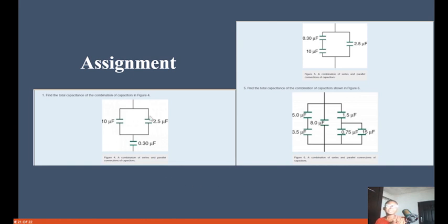So you can see this now. These two, you check, are they connected in series? Yes, these ones are connected in parallel. Then you are going to resolve it, and this one which is connected in series too, you have to resolve this first and change it to series before you can come and solve this. You know, in parallel you just add, and in series what do you do? You find the inverse, 1 over this. So the same thing goes to this place. You would find the equivalent capacitance and solve it, and also for